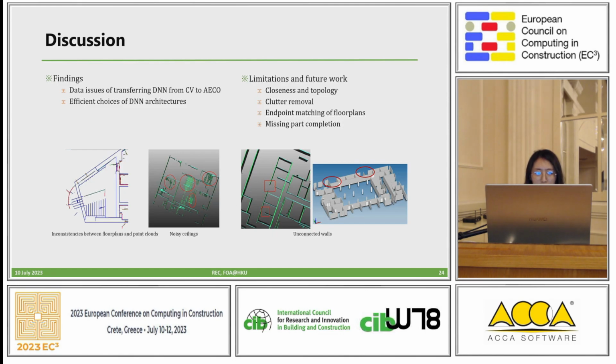But there are some data issues if we want to transfer DNNs from the computer vision field to the AECO industry. For example, in computer vision they mainly use much cleaner point clouds for 3D segmentation training. So to guarantee the results of 3D semantic segmentation by the SOTA DNN, we need to first segment the whole floor of point clouds into different rooms and clean some of the clutter inside the rooms to make the learning easier.